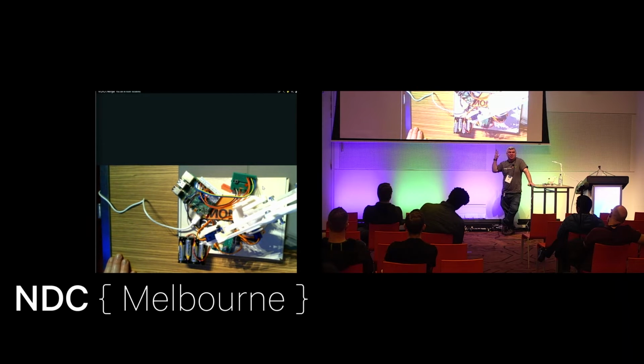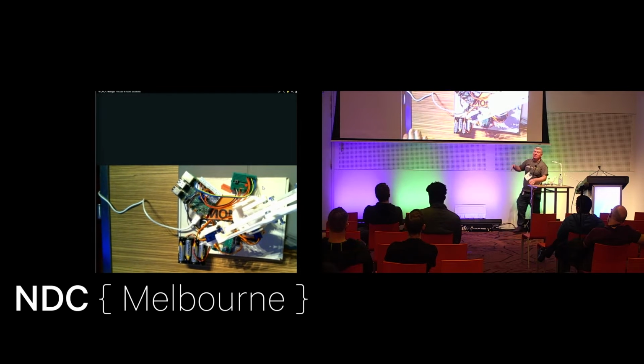So a Raspberry Pi is a full computer. It's got an operating system. So you've got to get that put onto an SD card, and then you've got to update it. That takes probably longer than it does to put it on the SD card itself. And then you've got to install, with my single line script, the .NET runtime, and then you've got to write your code and do it. With an Arduino, you write all that code on your PC, plug your Arduino in and flash the microcontroller on the Arduino, and you're off and running. So there's a difference. And the reason I point that out is that this isn't always going to be the best way you do your IoT projects.